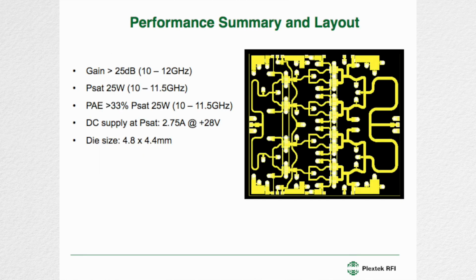And that's what the layout looks like. So you see these balancing resistors. These are very important. If anyone's going to design one of these, do include some balancing resistors. Otherwise, you can run into horrendous problems of loop instability. And things can look fine here and here, but inside you can get problems.